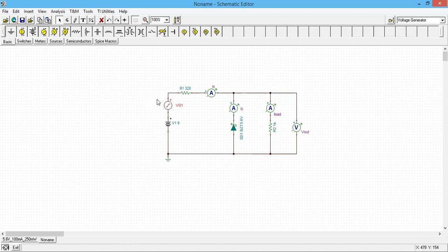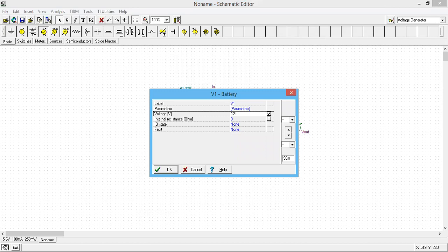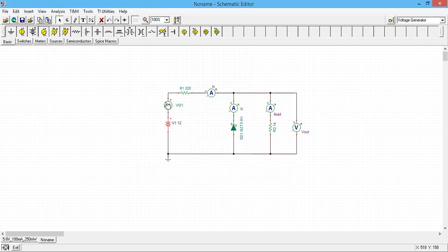That could be, basically, when you're driving these automotive vehicles, this battery is connected to different other power supplies, switch mode power supplies, generating noise. That noise is coupled via this battery's positive terminal to the rest of the other circuits. So in this example, if there's noise coming from other power supplies connected to the battery, we can observe what the output voltage looks like.